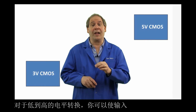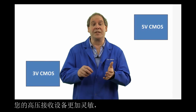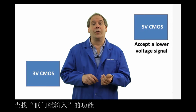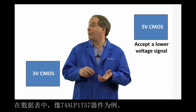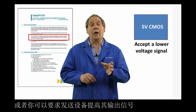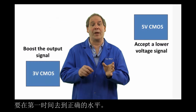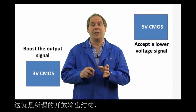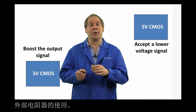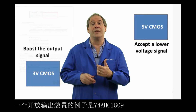For low to high level shifting, you can make the inputs of your high voltage receiving device simply more sensitive so that they can accept an input that seems extra low. Look for the feature called low threshold inputs in the datasheet, like this one, the 74AUP1T57, for example. Or you could just ask the sending device to boost its output signal to the right level in the first place. This is called an open drain configuration, where the output of the device is pulled up to VCC through the use of an external resistor. An example of an open drain output would be the 74AHC1G09.